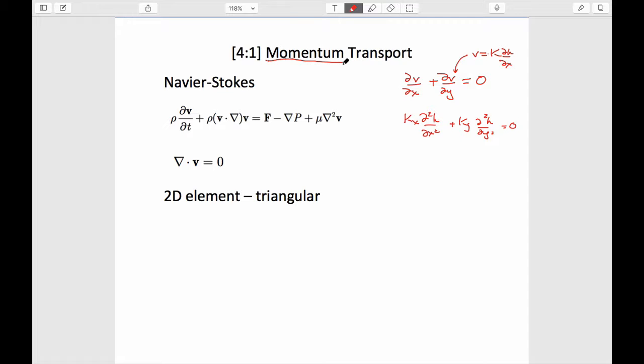Because what we're doing is, the Navier-Stokes equations come from solving a much more basic condition, and that is that we satisfy momentum within the system. And momentum really, if we wanted to write it out, is really just satisfying F equals ma. Forces and accelerations in a three-dimensional system, there are three of them, right? Forces in x, y, and z. And so you'd expect that we'd have three conservation equations.